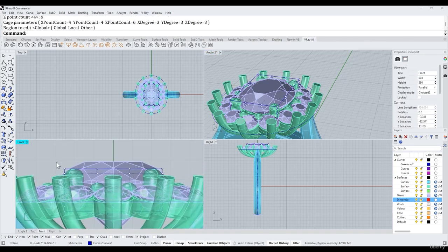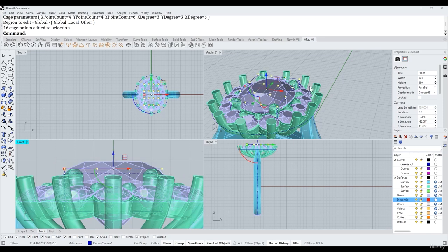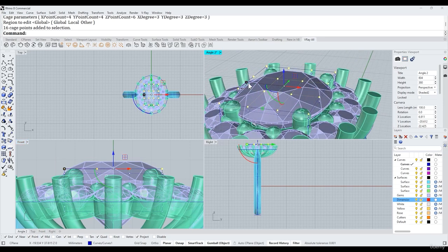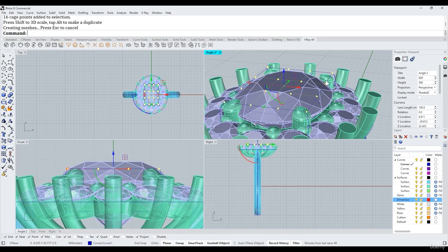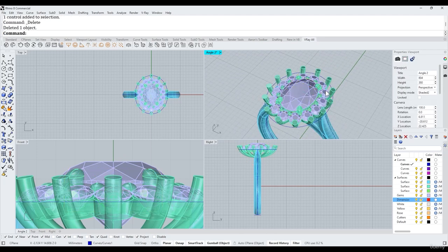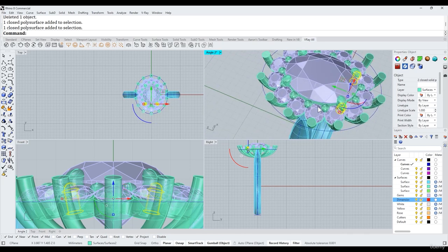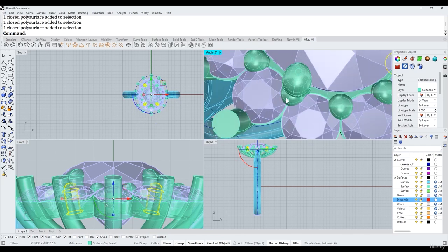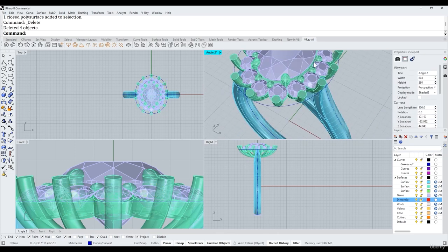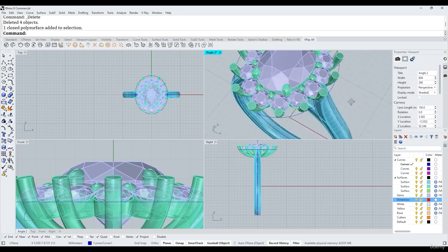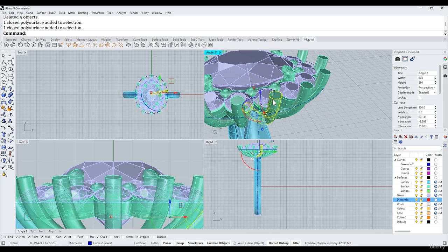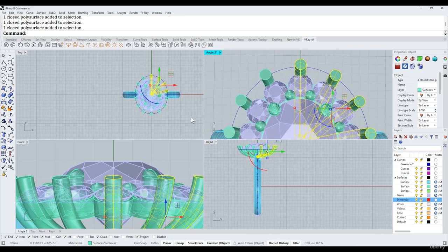Right click again. Select that top row of control points, that's that top layer, and holding down shift, I'm just going to scale this in, and that's going to bend those claws over. I'm going to select the top layer and the second layer, and just do that a little bit more again. Once I've done that, I can delete that cage. Now I've got these additional claws here, which Rhino's reinserted back in because we've got history enabled from our parent claw. But with those gone, then I can start working on these 4 claws here.